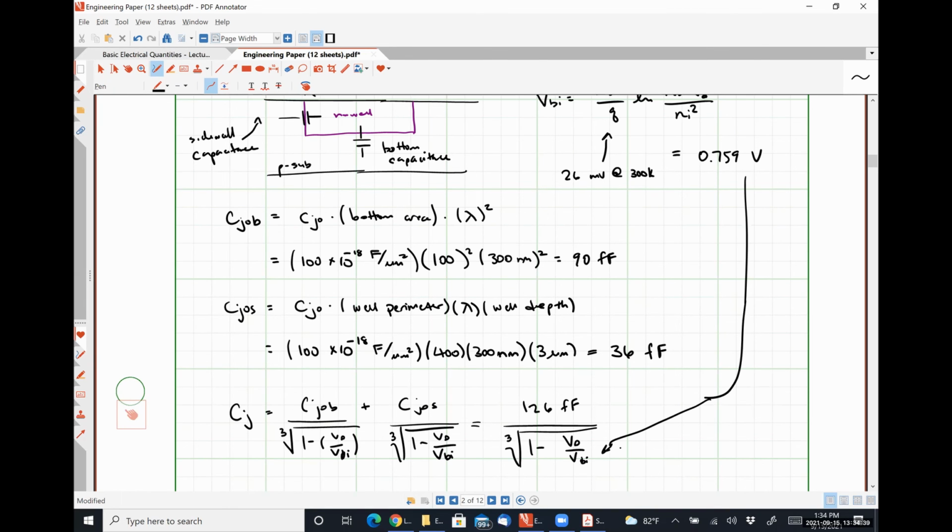But to go below that 24 nanometer threshold is enormously expensive because you can't just do simple things. So to get back to your original question, for a particular process, lambda is defined by the ability to reliably make something at that size, right? So it's all about the manufacturer. It's defined by the manufacturing process itself. It has next to nothing to do with the semiconductor material you're making your device out of. It's all about, can we pattern it smaller or not, and reliably. Okay.